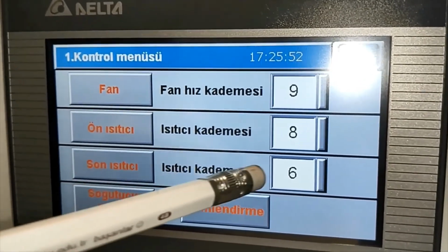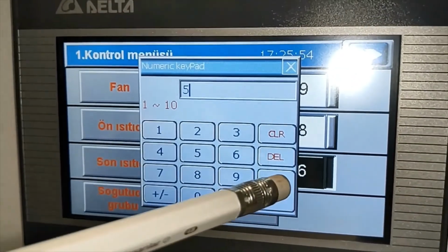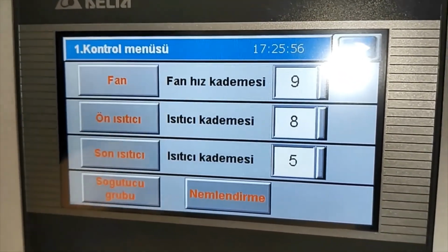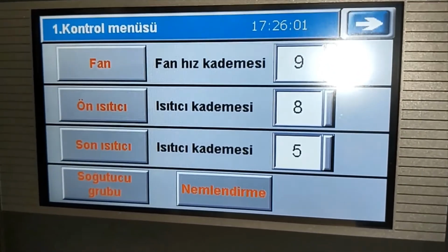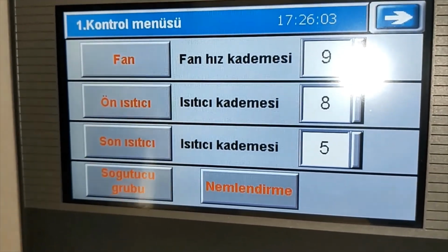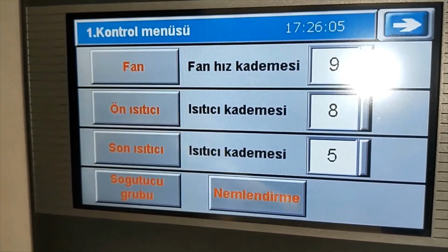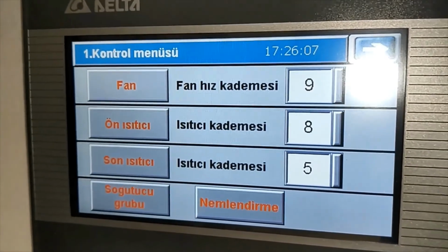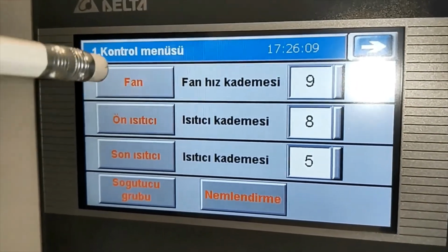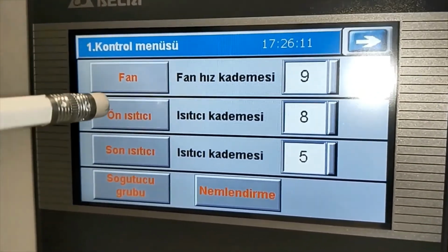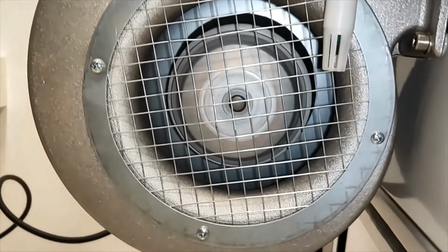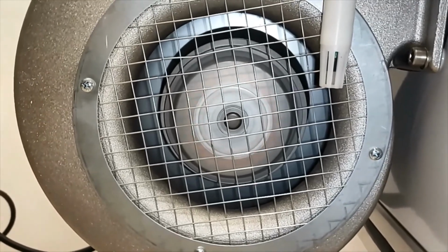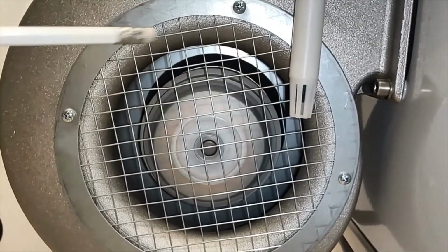The radial fan must be always open for winter and summer season, since it simulates the outside air. Cooler should be open because of the hot weather in summer, and finally after heater also be open, because the cooler cools air up to undesired level, but we want the ideal level temperature in living or working place. After heater provides the desired temperature level, and humidifier shouldn't be open since weather is humid enough in summer season.